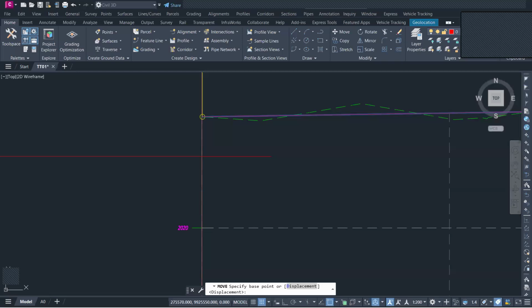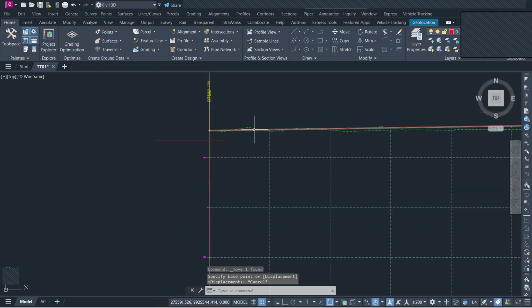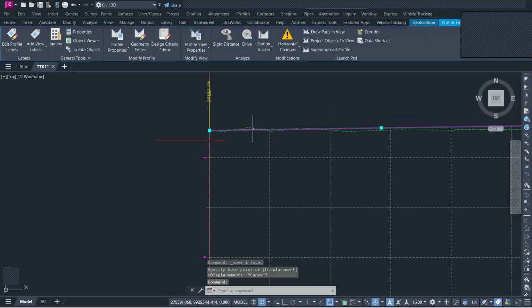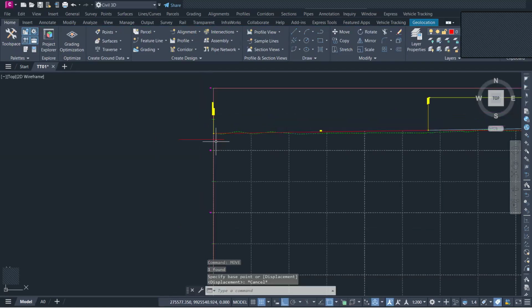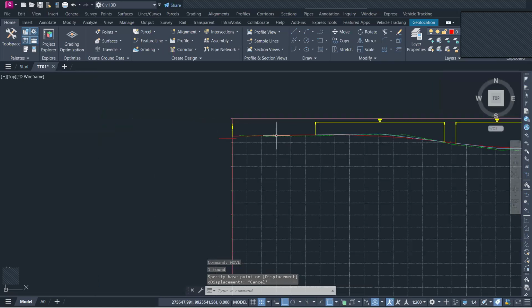Great. So what this means for us is we need to lower the finished road or rather formation level to somewhere like here. I'm assuming this is where the 300 is. So you select the FRL or the formation level. You make sure you've turned on the other mode. And then once you select it, you hit what we call move. Now, the question will be, how will you determine where the 300 mm is?